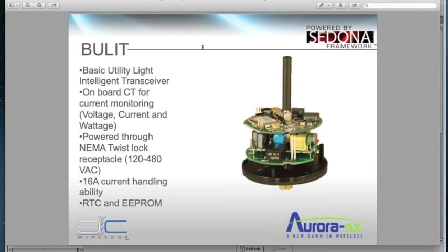Because the device also has a real-time clock, EEPROM, and backup solid-state battery that is an energy harvesting device, this device now becomes a standalone controller, not requiring communication from the JACE. So you could technically deploy this system across a college campus, a municipality, hospital, mall, what have you, and lose communication from the JACE, and the devices will run on the last known schedule that has been uploaded on a weekly or bi-weekly basis based on sunrise, sunset, and or Julian calendar scheduling.